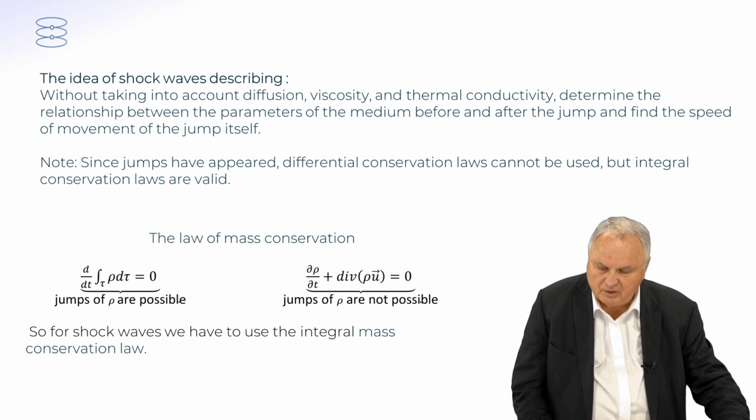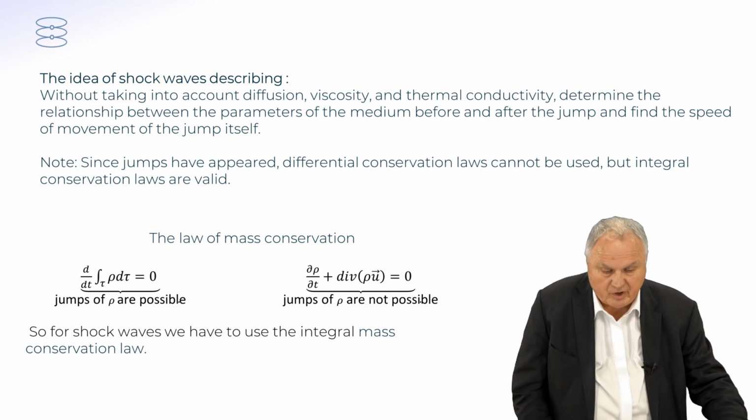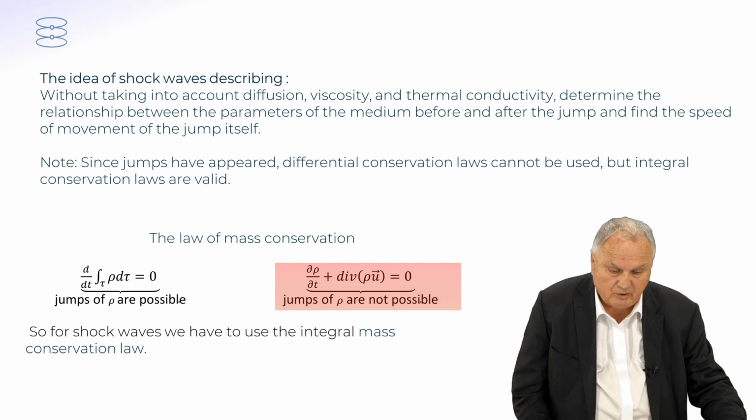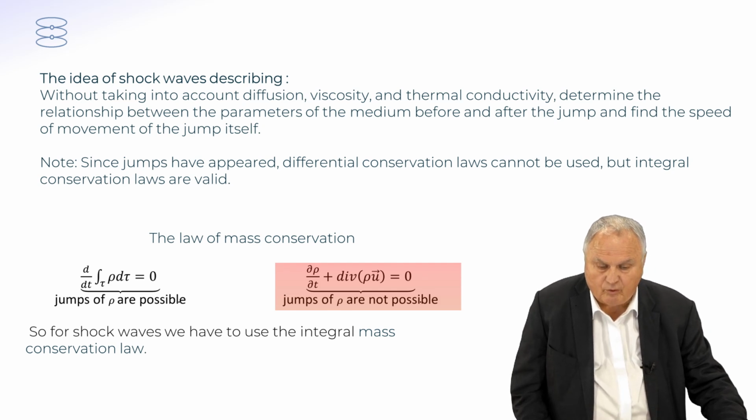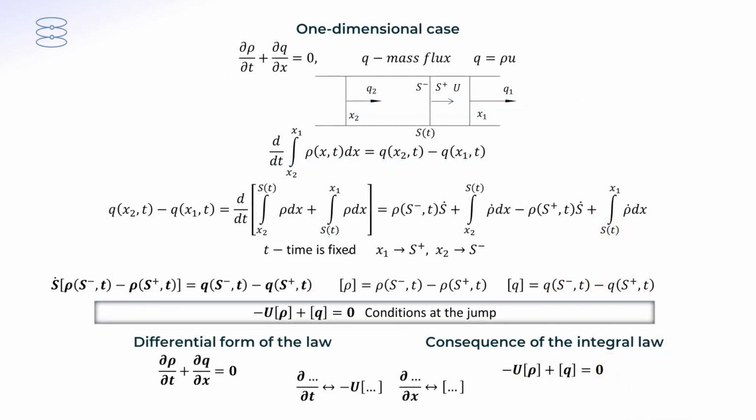The first one is the integral law of mass conservation. This is here. And here jumps of density are possible. In the differential form of the law of mass conservation, jumps of density are not possible. So, for shock waves, we have to use the integral laws of conservation.